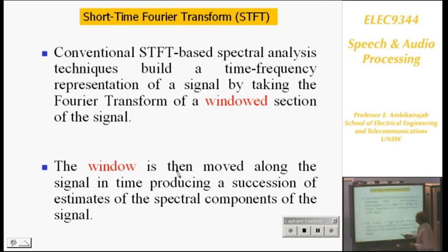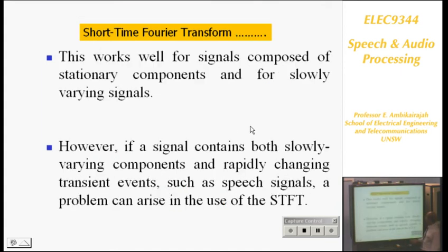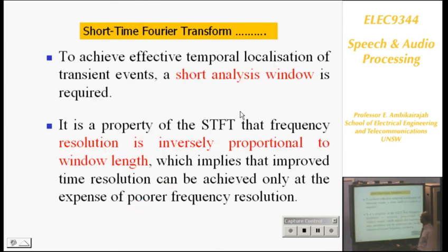So short time Fourier transform, we already know how we do the short time Fourier transform. You use the window. I have already explained this, so I don't need to go through that again. This is a recap of what I have already explained, and it's the problem with the short time Fourier transform because of the fixed frequency and time resolution. Resolutions are proportional to window length. That's the main part that you need to know.